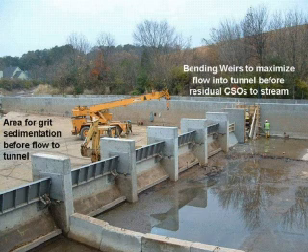This is a graphic of the typical screening facilities before the tunnel. Each facility includes chemical disinfection storage areas for sodium hypochlorite, the pumping systems for that sodium hypochlorite, and sodium bisulfite to dechlorinate further downstream. The core screens and the drum screens take out the solids in the flow stream, and they're dumped on the floor, and the materials removed from that area into dumpsters.